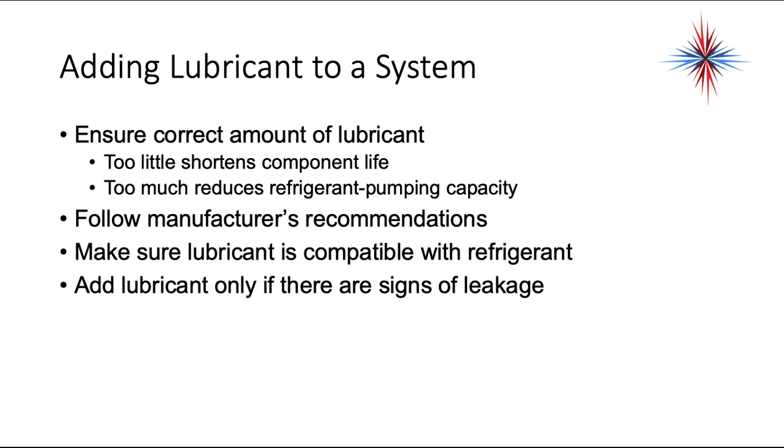When adding lubricant to a system, make sure you have the correct amount of lubricant. Too little shortens components' life, specifically the compressors. Too much reduces refrigerant pumping capacity. Follow the manufacturer's recommendation. Make sure the lubricant is compatible with the refrigerant. Do not mix lubricants, and add lubricants only if there's signs of leakage.